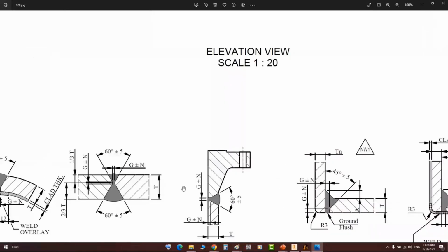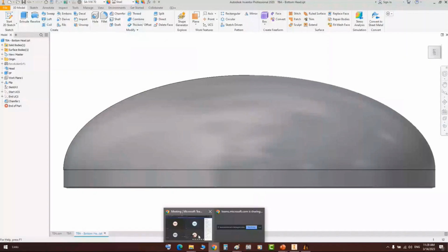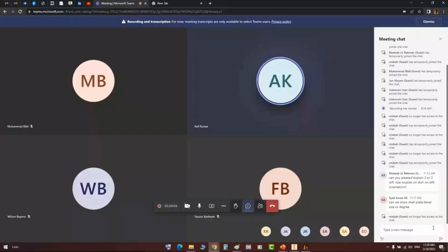Okay, we understand that. Which means in the 2D drawing we can show a typical weld detail, no need to show it in the 3D model. Yes. Because a lot of welds will increase the size of the part, and that will increase the number of lines inside your drawings. That will take memory, not a huge memory, but sometimes you decide that it's not important in your drawing, so no need to spend the time to create it.